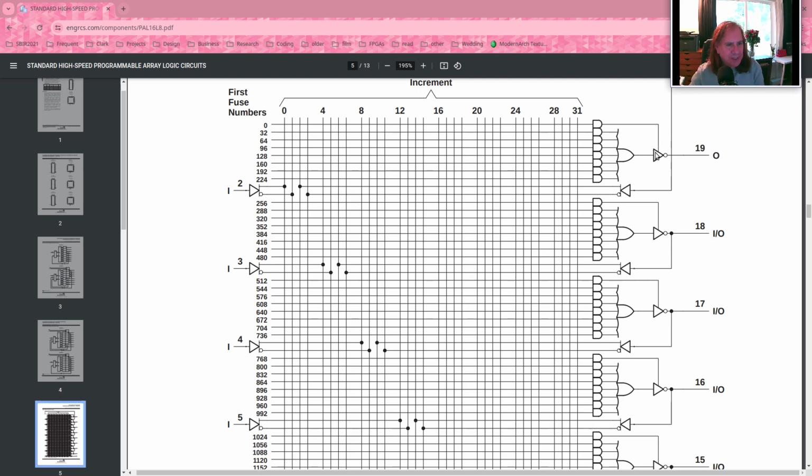This device right here is called a tri-state output, and it's a way to electrically disconnect this output from pin 19 in this case. If we put a 1 into the side of this triangle, this acts like an inverter. But if we put a 0 on this wire going into the side, it's as if this device did not exist. It's as if there's an open wire between here and pin 19.